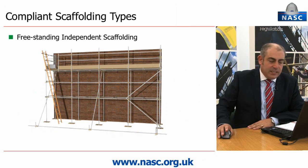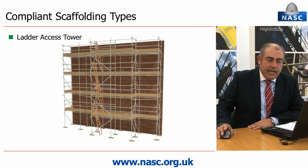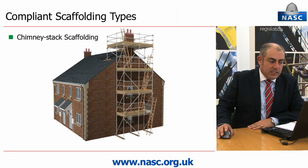freestanding independent scaffolding, stabilised with butting transoms and ground rakers, loading bays with variations for 10 kilonewton or 15 kilonewton loading capacity. Ladder access towers are butted to independent tied scaffolds and chimney stack scaffolding.